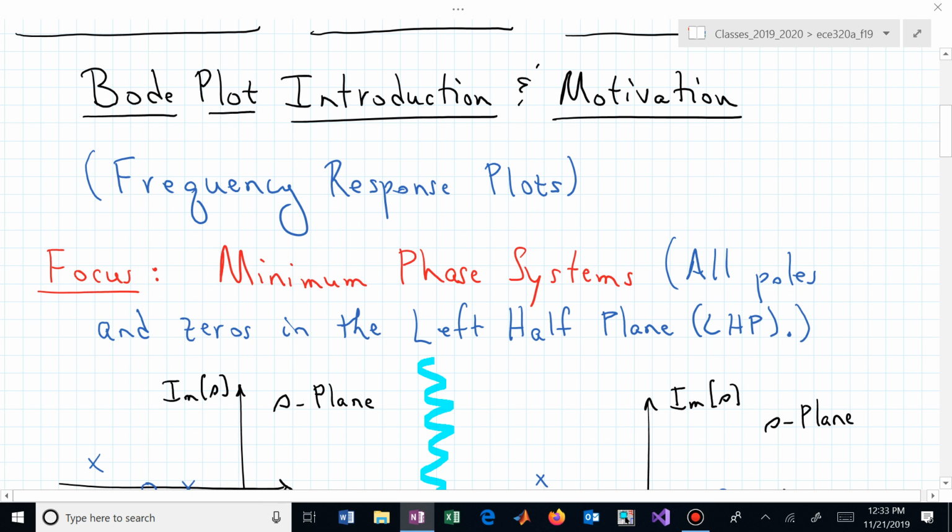The other thing that I might inject occasionally is octave versus a decade. You might be thinking, oh, there's 8 notes in an octave, but in terms of what we want to remember, an octave is a factor of 2. A decade is a factor of 10. So if I say what's happening an octave from here, and here is omega equal to 4, then you would say, what's happening at omega equal 2 times 4, or at 8?